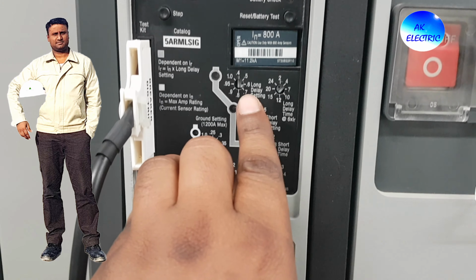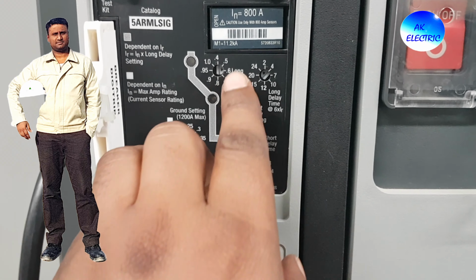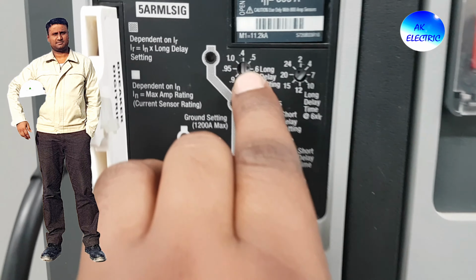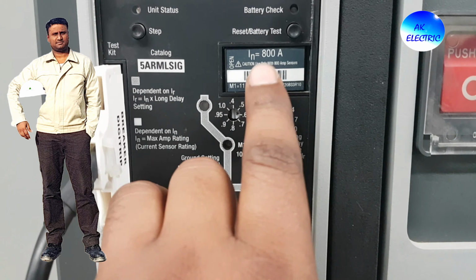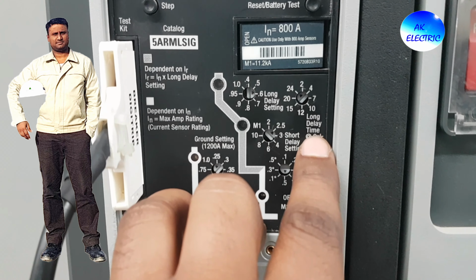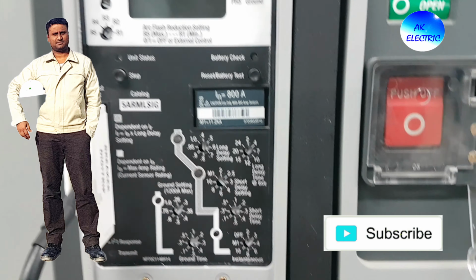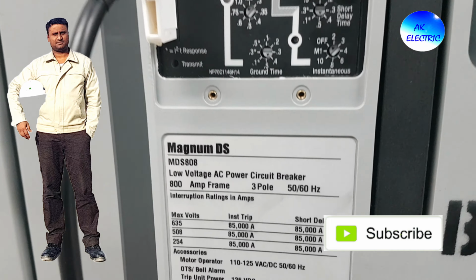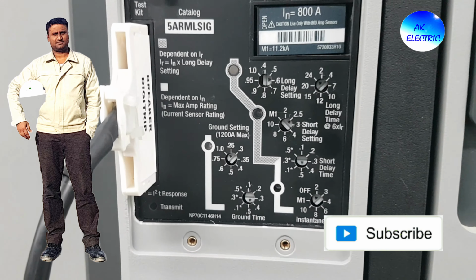Before that, let me explain the long delay and short delay. See here, this is the long delay setting. If you put this arrow mark at 0.4, that means 0.4 into 800, and then that value you have to calculate times 6.